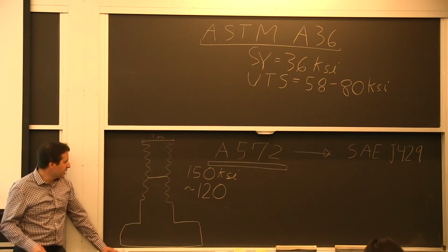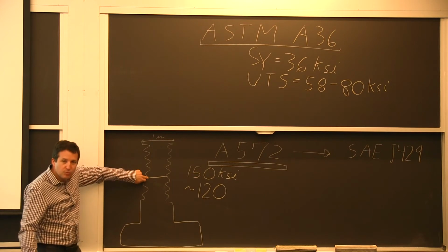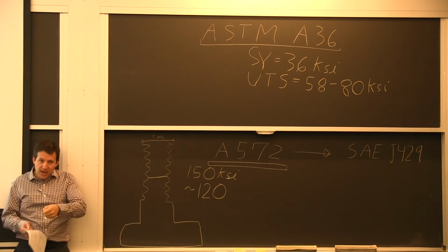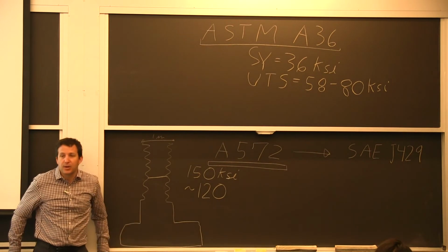Now, if I consider all the stress risers associated with a root like this, even if it's just pure tension going back and forth, I'm likely to have to knock this down by about a factor of 5.